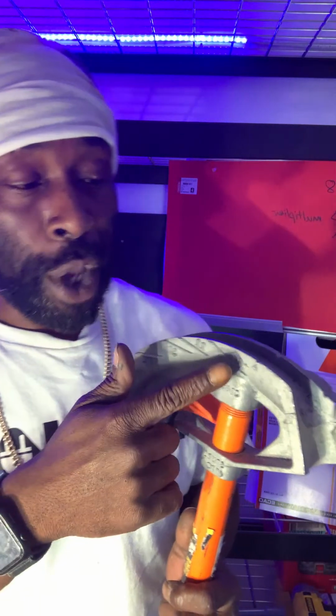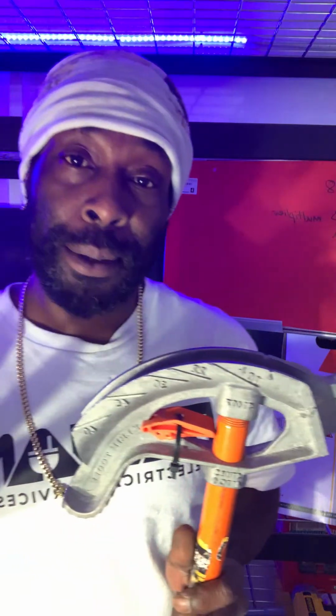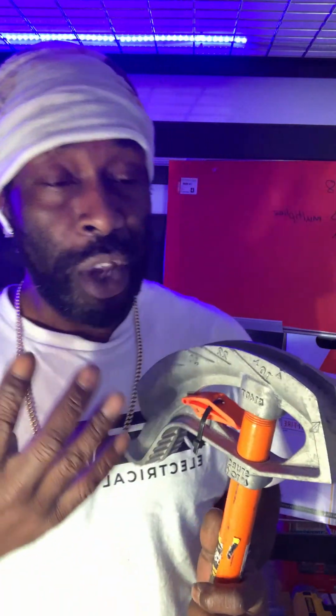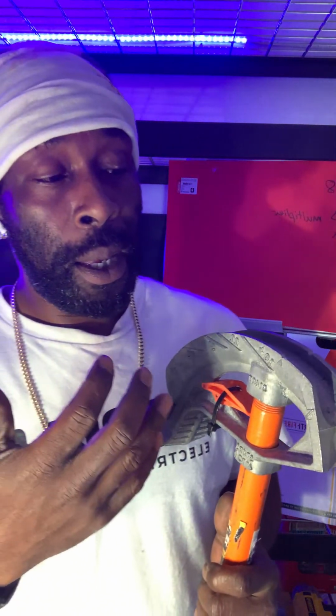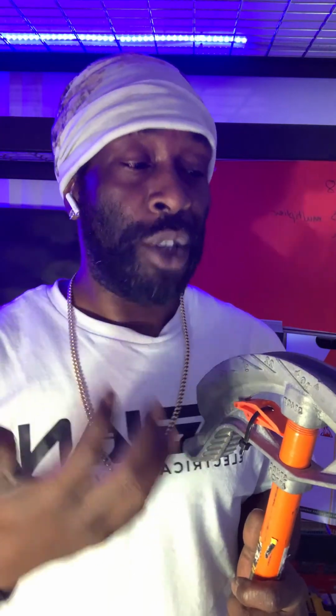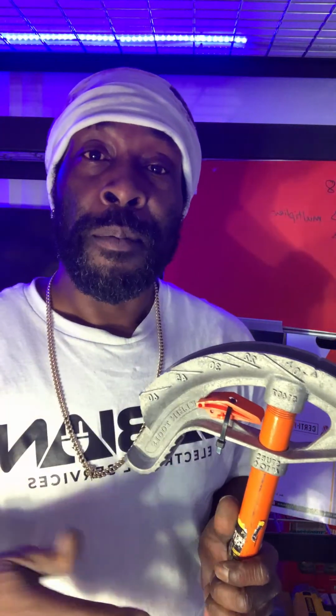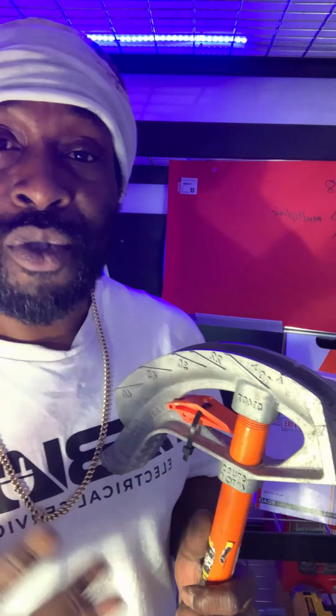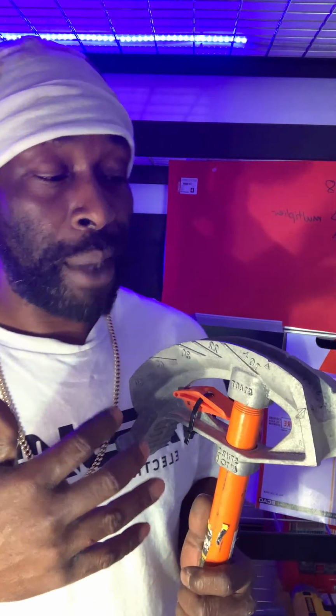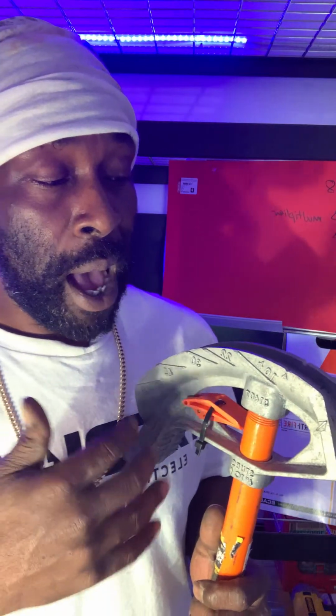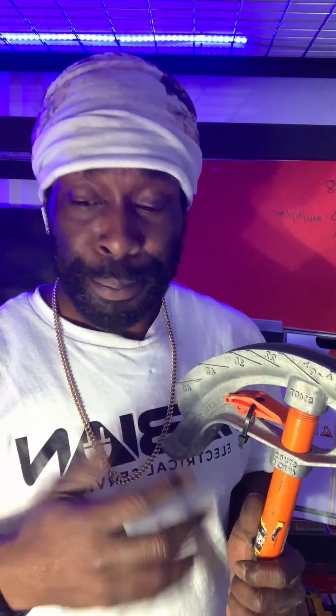When you use your star, you don't need to deduct. The star is basically going to give you a little bit extra on your pipe. It's going to take away that shrinkage that we are all afraid of. Shrinkage reduces your measurement. You're going to lose pipe on the bend.